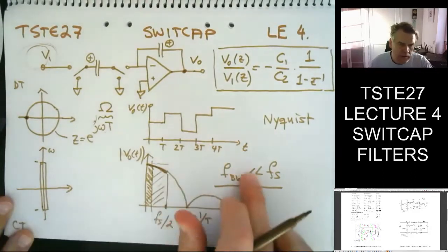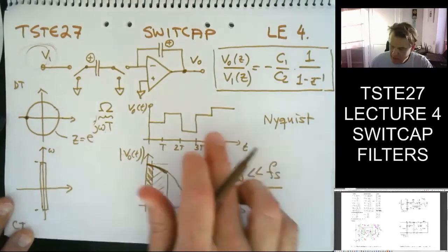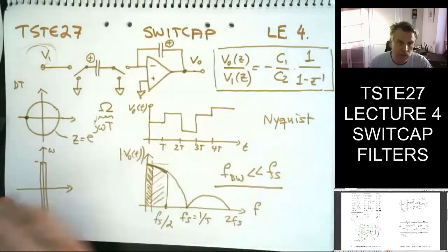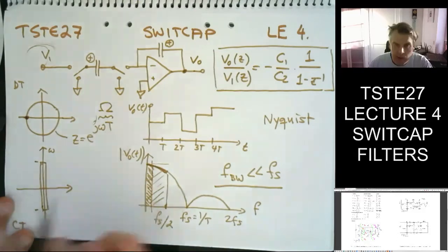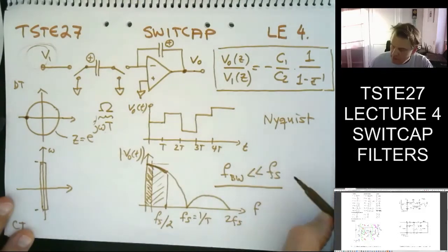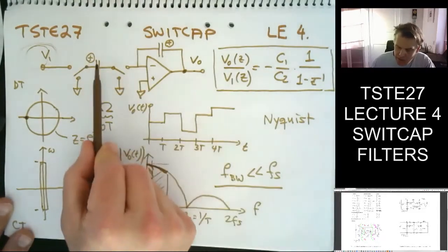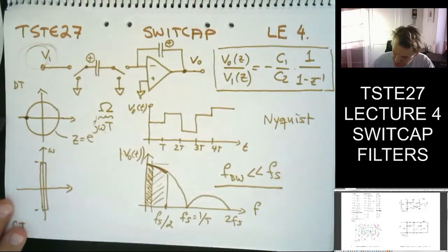So one could argue that this is a bad requirement for switched-cap, but remember we can probably switch the switches today quite fast, and also the op-amps we can do quite quick with high bandwidth. You have 500 megahertz bandwidth in your lab 1. And again, we have the improvement over this typical continuous time integrator is that we don't need a resistor. So that's the benefit we have.